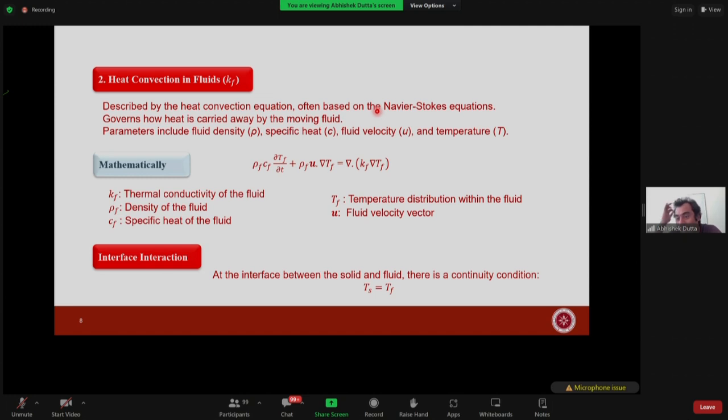No, it is not going to be satisfied. So what you have to do here, this is a problem. I know, and these are very practical problems. Here, because you are going to do these numerical calculations, you will be coming to these numerical issues. One easy solution is you have to live with this temperature jump, but this is not correct. The other solution is to refine your grid as much as possible so that you can touch the boundary layer. This is one option, but this makes your problem very, very complex in terms of time. And I've been mentioning this in my later slides, as you have said. So this is one problem.